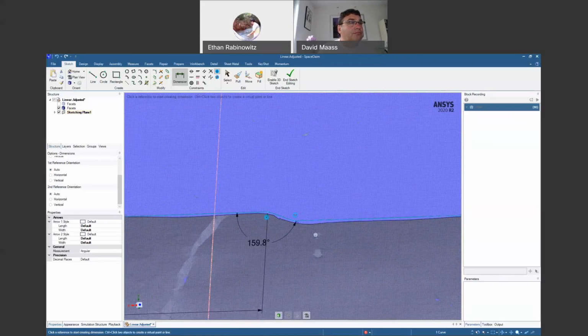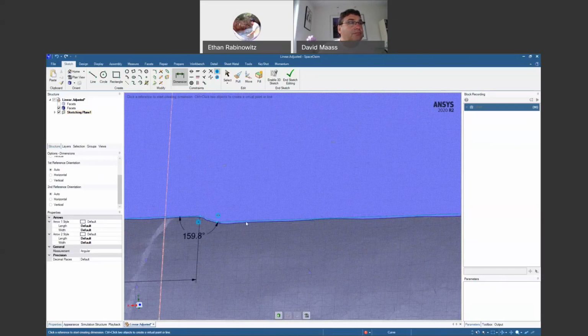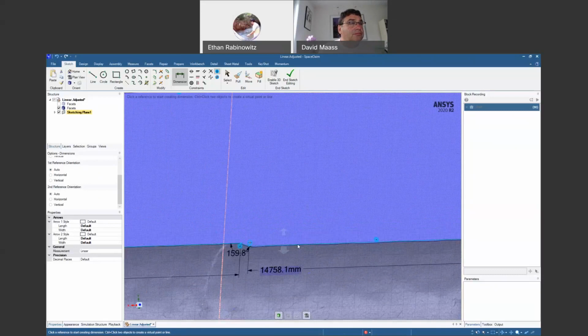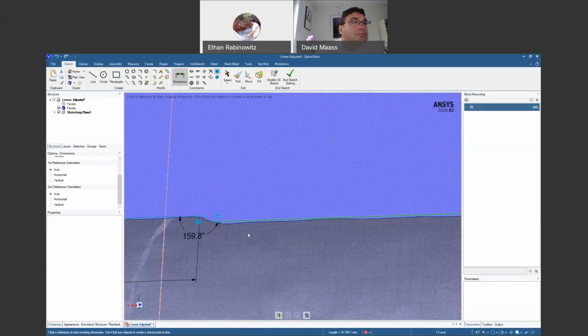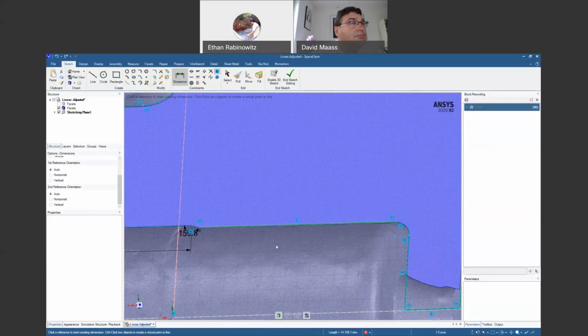Grab an angle there. I'll probably have to put lengths and things in, but I'll just do some of these. Oops, undo that one. So you know, Windows shortcuts work, like I did Control Z to undo that. Also, when you dimension, I need to dimension between 2 points in order to get this corner to this wall. Where I place the dimension determines the orientation.